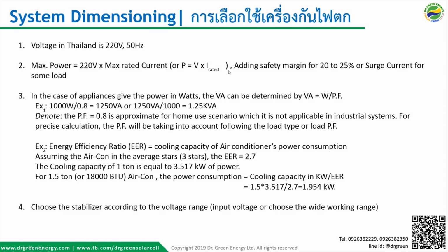Alright? And normally, after the design, we will also keep a safety margin of 20 to 25%. Okay? For the surge current of the particular load, for example the pump, the water pump, or the traditional air conditioners. And we can discuss the design from number three that we are going to discuss here.